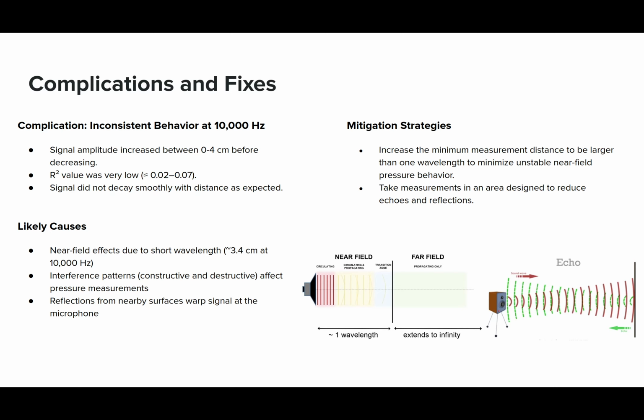So some strategies to mitigate this in future testing. I would increase the minimum measurement distance beyond 1 wavelength and also conduct tests in an acoustically treated room to reduce reflections.